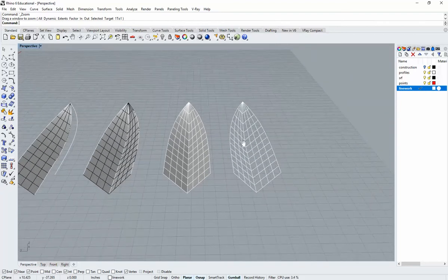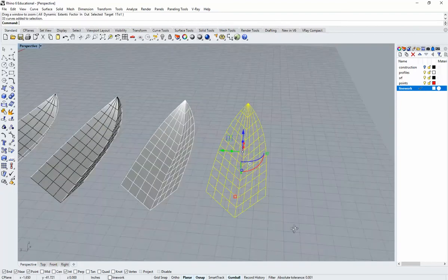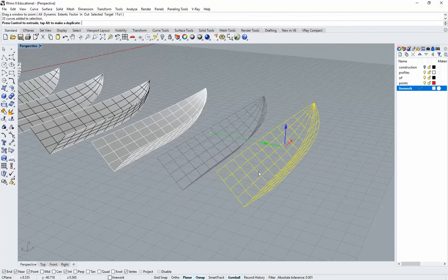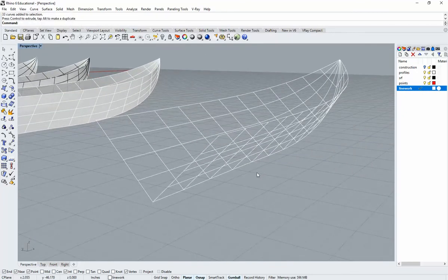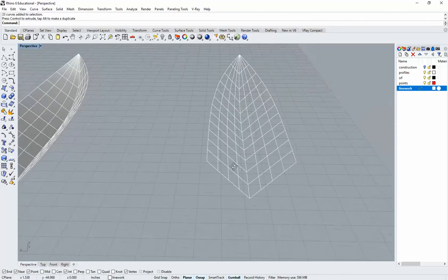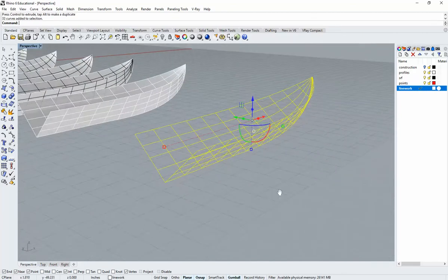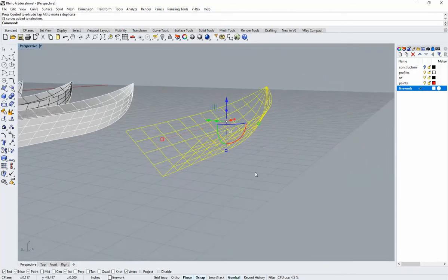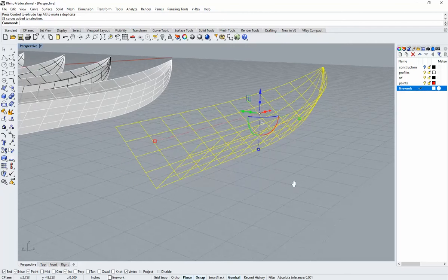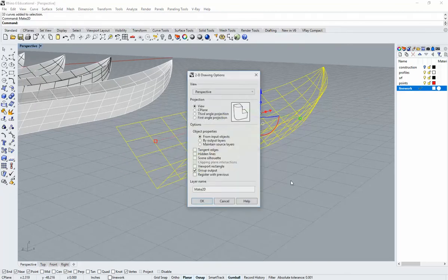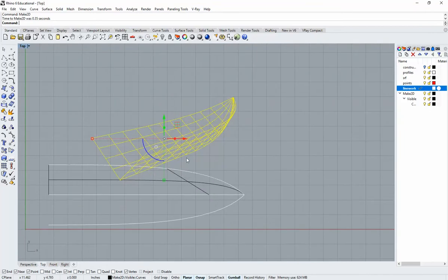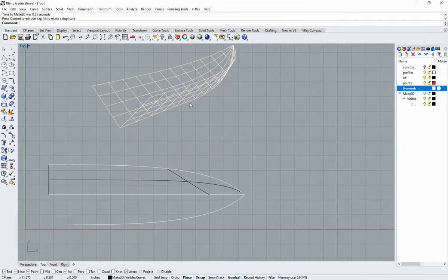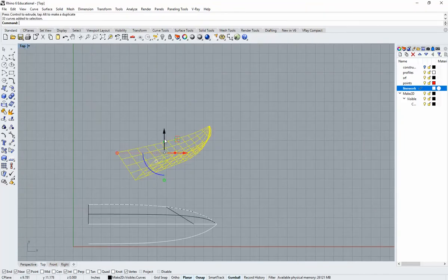Now, let's walk through a really quick make 2D trick, and you may already be aware of this. To start, I'll show the first version of this, which is to do a make 2D of the wireframe, and I'll select a view like that. You can follow along and select a similar view. Type in make 2D, let it run, have a look. And of course, no surprises here, it's going to give us this X-ray view, this wireframe view.